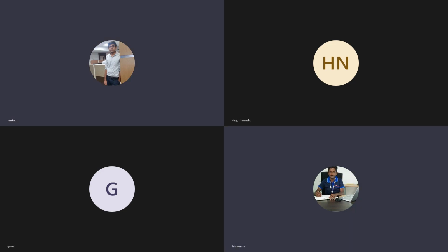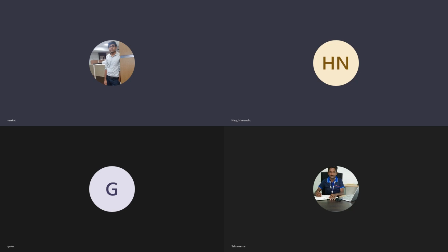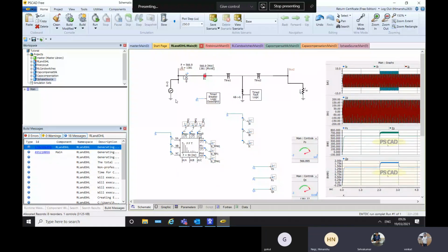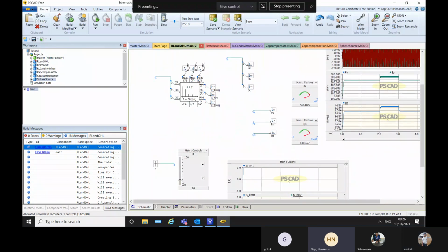Yes, sir. I think he knows about the modeling of sources. I hope you can model a source, because what you are showing me here is a model. I didn't model it as a regular impedance or source. I just modeled an ideal source, and I tried to use breaker logic. I copy-pasted a line from the existing project for the logic, a variable load, and then tried to control that load by this.